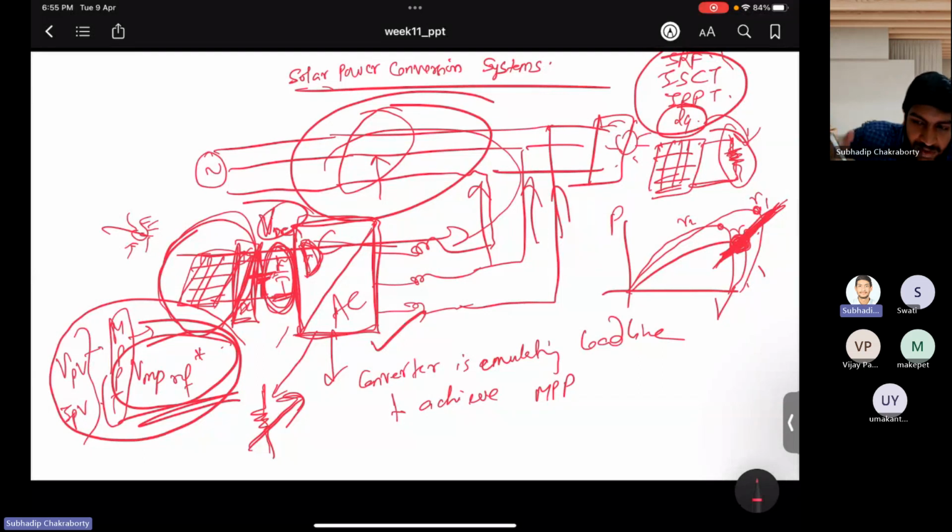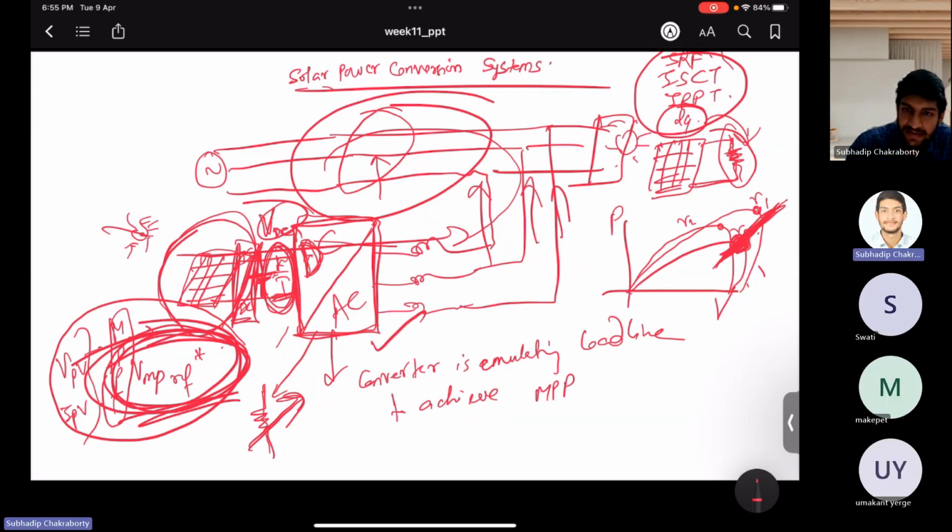The battery is maintaining the output of that converter, and the input is regulated as per the control algorithm, where the control will work to generate the input voltage across the PV, same as the VMP reference. Once you impress that maximum power point reference voltage across the PV for that given irradiation, only then will the PV deliver the maximum power as per the variable load line. As I told you, it should emulate that particular resistance value for which I am setting the load line. For that particular resistance value only, that characteristic will coincide with the maximum power point of your VI characteristic.